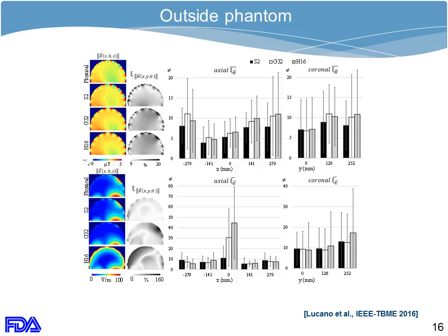So again, if you are interested in something that is happening inside a phantom, then you may use a model like the H16 or G32. But if you are interested in the electric field, and maybe you have a device placed between the phantom and the coil, so close to the coil, then models like the H16 may not allow an accurate representation of the physical.